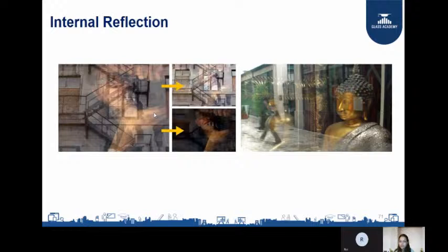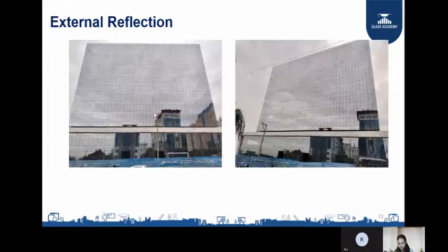Now, how to find total direct heat gain? For that, you have to multiply the SHGC or the solar factor of the glass with incident solar energy. Now, incident solar energy is what? It is the intensity of the sun at a particular location. Say if I talk about Mumbai, my incident solar energy might be different from Chennai, Kolkata, or Shimla, right? Mumbai, Chennai, Kolkata might have higher incident solar energy, whereas Shimla, Manali might have lesser. It depends on the location.